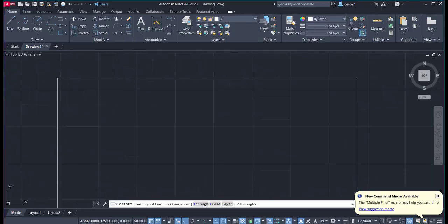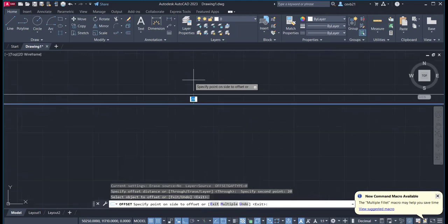So you just click the distance, and then for example 20. So click, you see, you can click outside or click inside. Which one do you need? So if you want a larger one, you can just click outside, or a smaller one, you just click inside. Okay, so you can have it multiple. Okay, when we zoom out, you can see that is how you use offset.